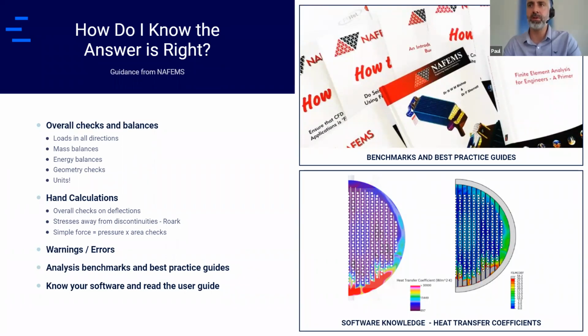So the heat transfer coefficients are completely meaningless unless you know what that reference temperature is. And so really, when you're exporting a heat transfer coefficient from a CFD software, you actually can't just export heat transfer coefficients. You've got to export the reference temperature along with them.